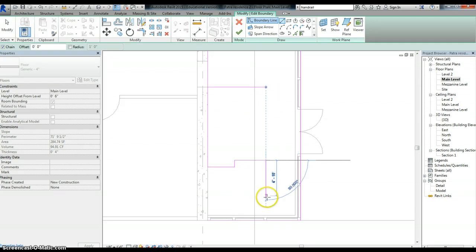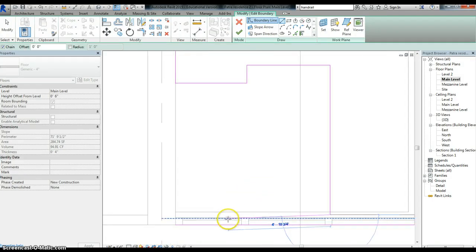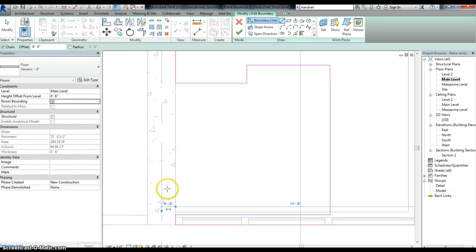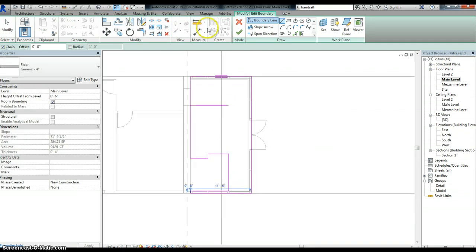As we see, we were lined up there, and then we're going to come down 7 feet 7.5 inches. And we're going to be just inside the mullions. Hit that wall. There. And what I want to do is go up here and delete that reference line.